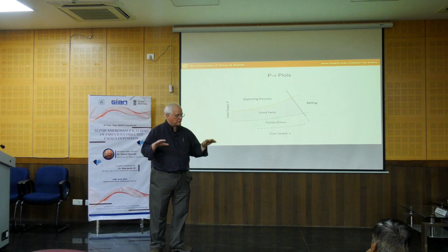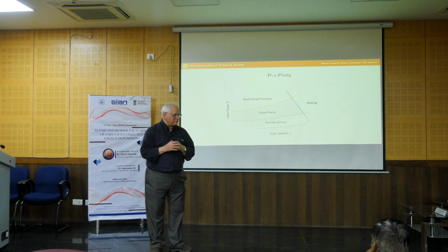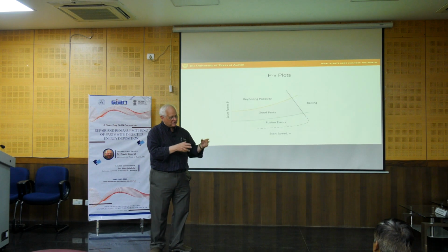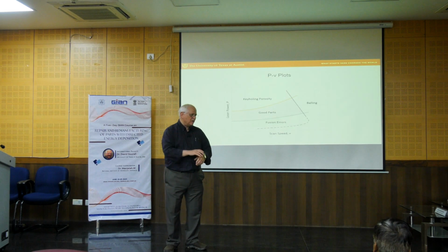Those tend to be the two trade-offs. Clearly, we could argue that if you move to laser-based DED, you can do better part quality in terms of geometry, and with powder bed we can speed up the process by using multiple lasers and other things.